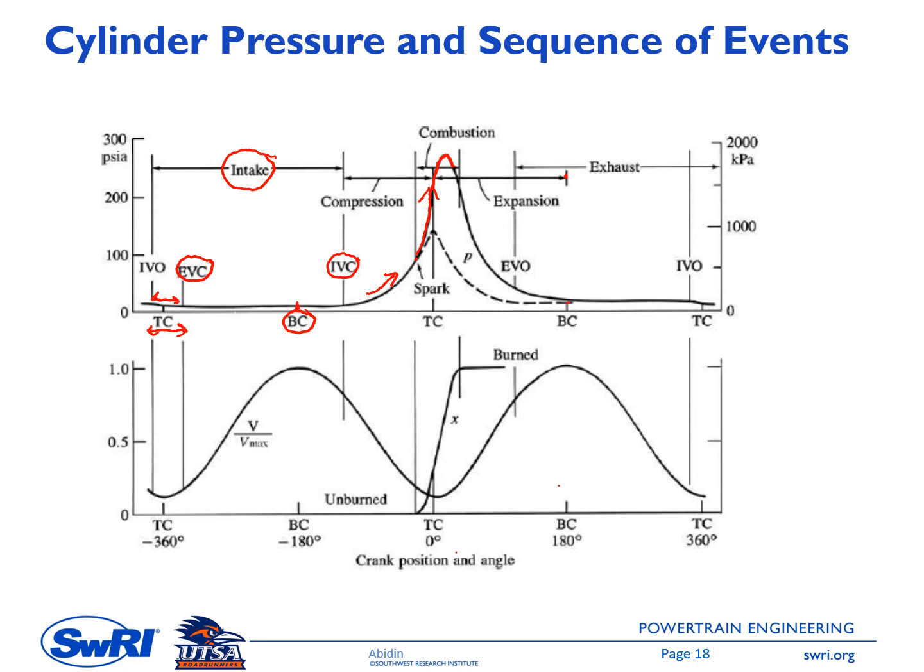Okay, but you can see in here, as I mentioned in the previous slide, the exhaust valve opens before the piston hits the BDC. The process between this point, the exhaust valve opening, up to BDC, is called a blowdown process. There will be exhaust gas exiting the chamber because of the pressure difference between the chamber and the exhaust manifold.